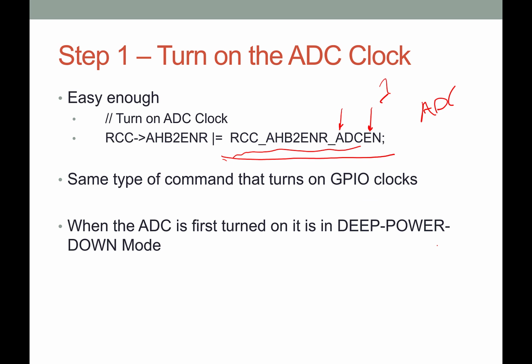So you're starting the clock, and then you have to take the analog to digital converter out of its power down mode. If you've just turned it on via the USB port, it should be in the power down mode. In fact, one of the weird things with my firmware was that it started out in a power down mode before I updated it, and you couldn't even wake it up. I had to do a special setup that was requested on the author's website.